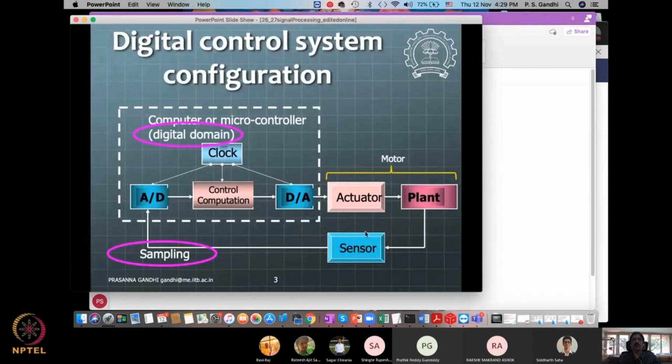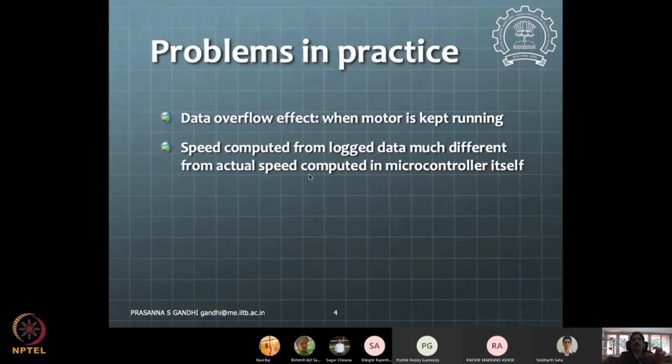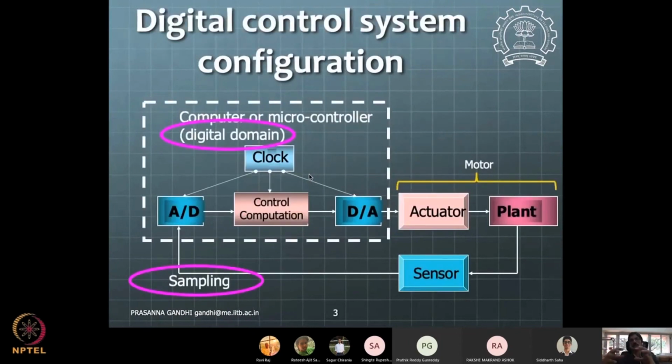Normally what we do is we develop some controller in the analog domain, and we say, with enough fast sampling time, I would be able to implement it faithfully in the digital domain. Fine, and then our job is finished. We say I have enough fast sampling so that this controller will behave as if it is a continuous system. Fair enough. That is also a good argument. Many times people use that, and they don't bother about getting into digital analysis itself.